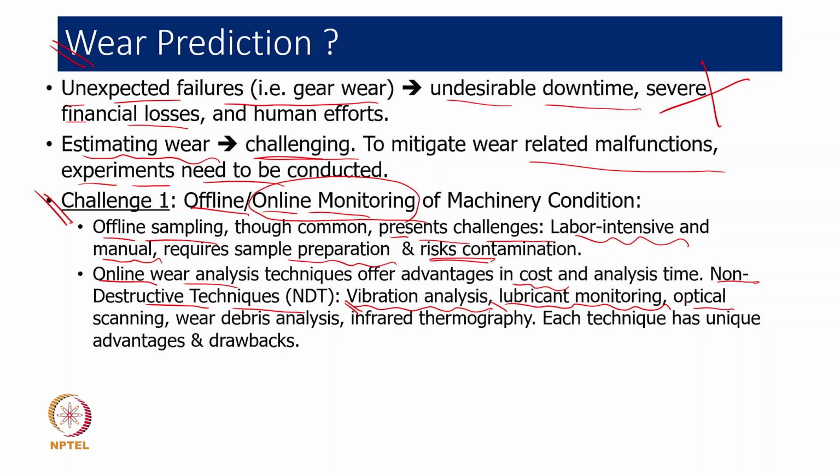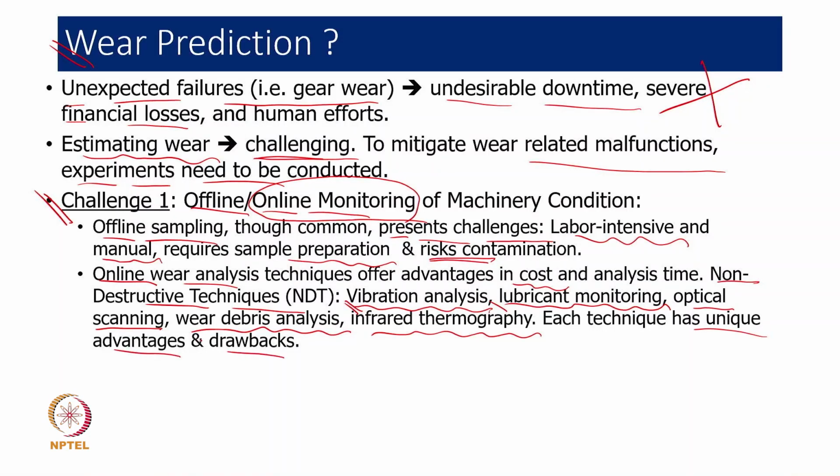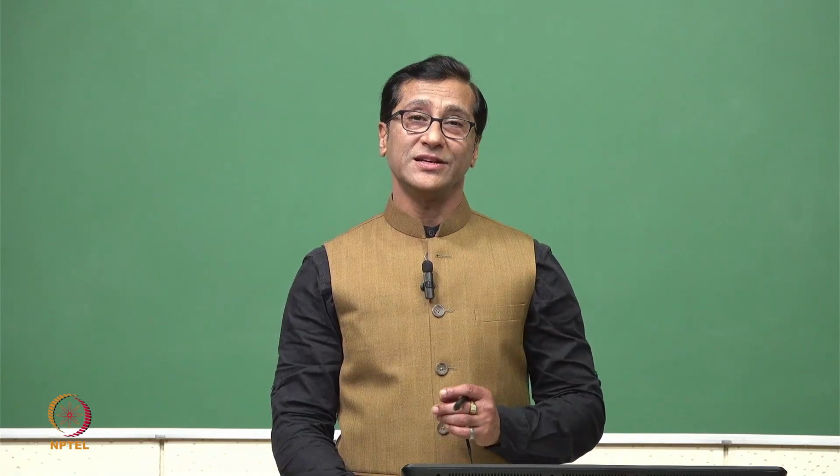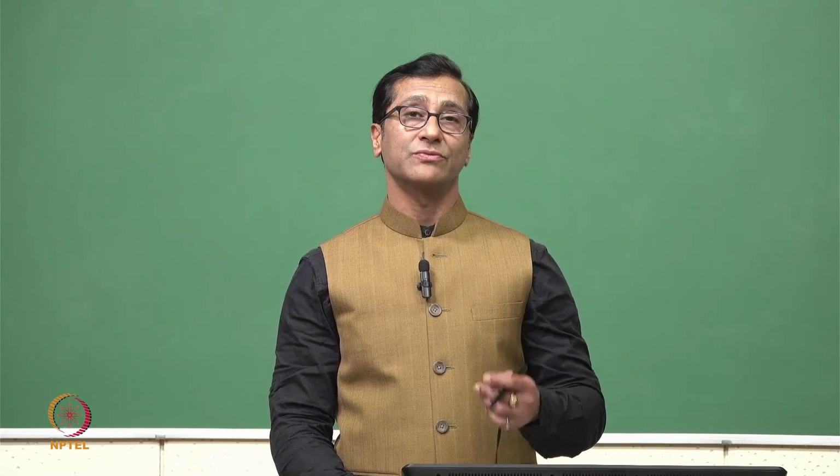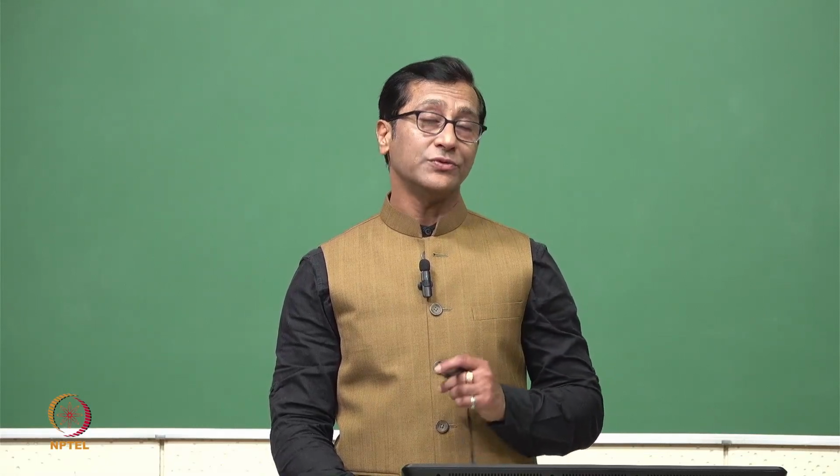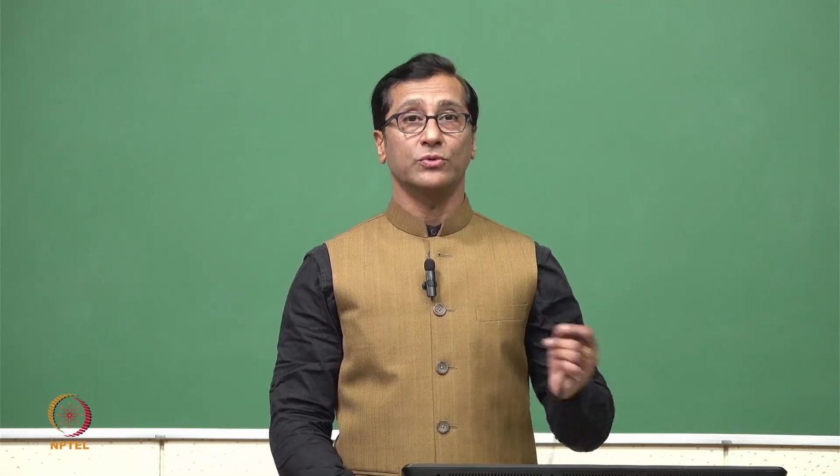Or sometimes we are now starting with optical scanning of the surface, which captures surface degradation. We may be discussing more about wear debris analysis, whether that is also sufficient. Now another technique has also emerged, infrared thermography, where we get a thermal image and analyze that. So there are very many techniques available, and each technique has unique advantages and disadvantages. The question is, are we able to integrate two or three of them and come up with better results? For that purpose, we again require data fusion, and